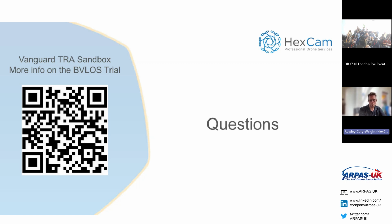You have to start off with a tolerable level of safety. And we essentially followed the SORA 2.5 guidance, which gives a 1 times 10 to the minus 6. So that's a 1 in a million chance of harming or killing somebody on the ground. We've gone above and beyond that because we didn't go through the maths of, if your drone strikes somebody, what's the probability of killing them. We decided not to go through that particular exercise. We just decided we wouldn't want to cause harm to anybody. So we've gone down the route of a 1 times 10 to the minus 6 chance of harming anybody. So again, it's just a fairly complicated mathematical process of proving the probability. And again, Owen's your man to talk to on that particular side.